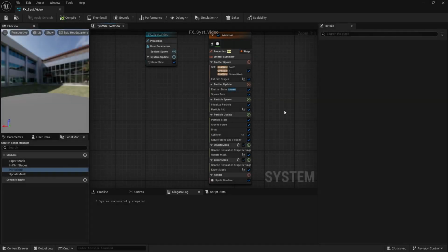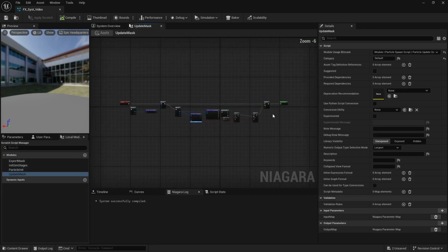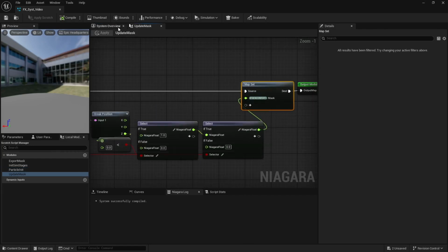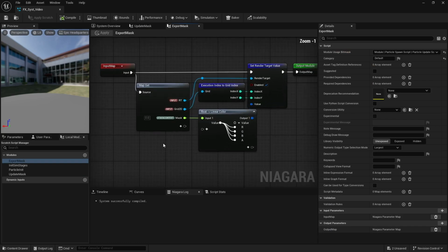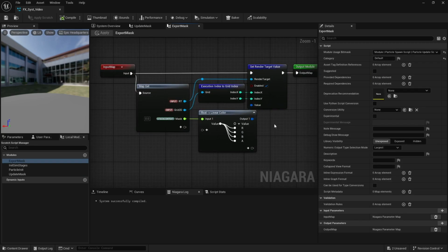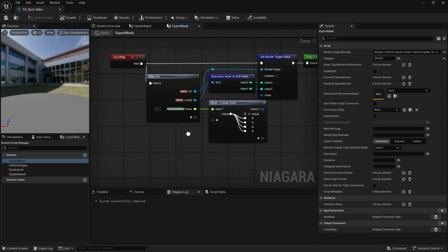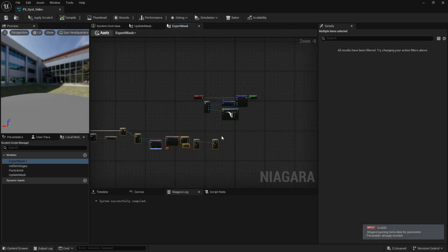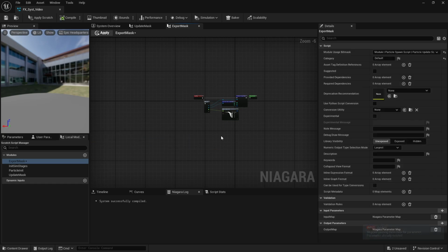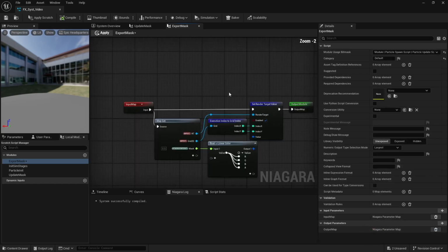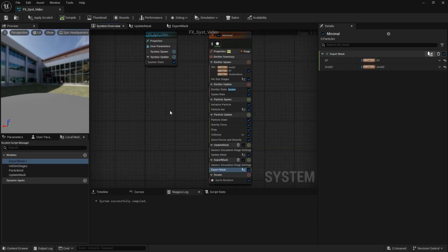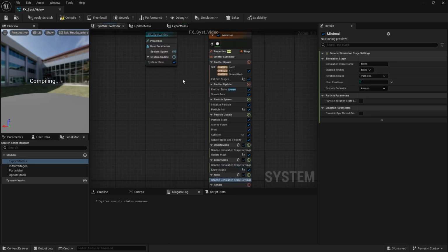You might have noticed I used a Grid2D interface to do things in two different steps. First, I compute the wetness value, and then I output it to the render target. But I could have computed the value and output it to the render target in a single simulation stage. But I chose to do things this way because it allows me to create a feedback shader quite easily. See, I'm going to create a new simulation stage to iterate on the Grid2D, but only once upon simulation reset.